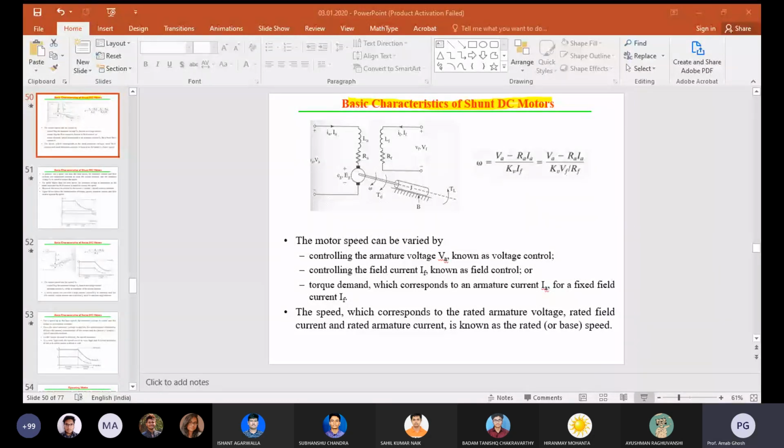Then what are the different operating points? We are now discussing dynamic braking. What happens in dynamic braking? In the arrangement, RB is your braking resistance, the dynamic braking resistance. You remove the load and connect this resistance. Additional energy is dissipated through the armature resistance and RB.